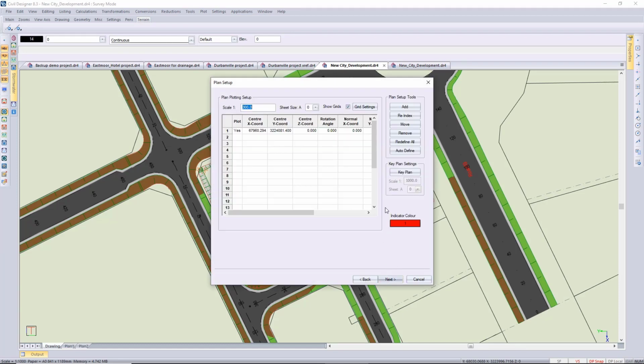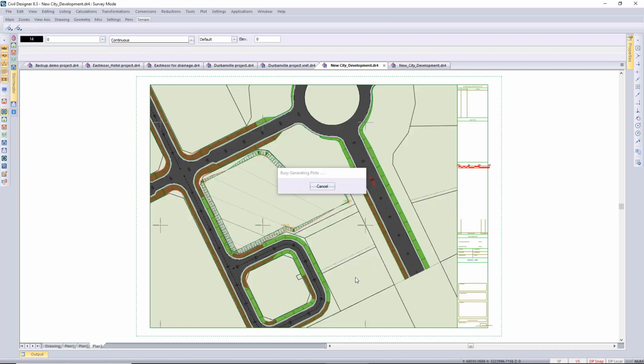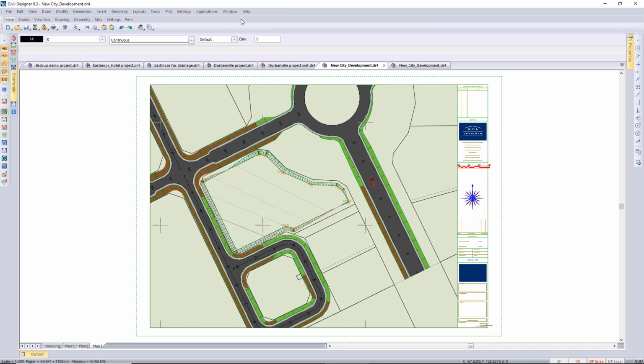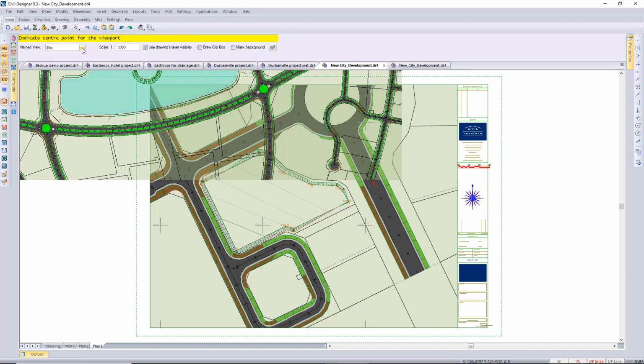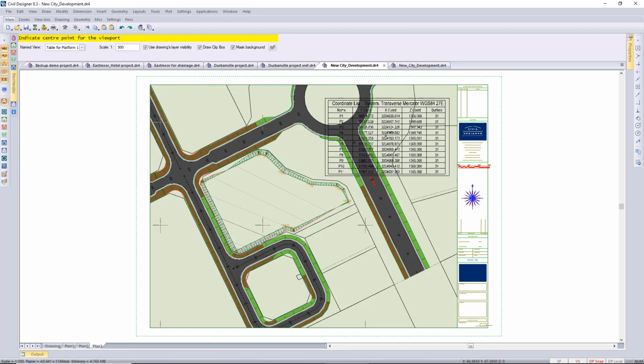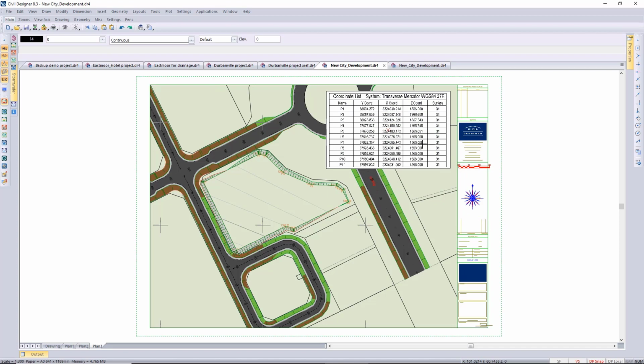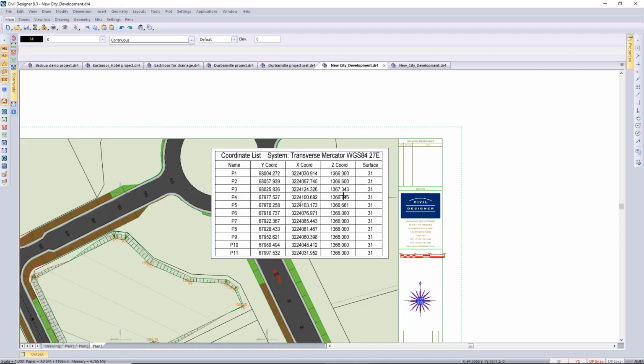Using that same define plot area, I'm switching off that list to plot because we're going to load the viewport. So that would be in the CAD, unless using the toolbar, we can go layouts, add viewport, and select the correct viewport. You can draw a clip box and you can mask the background behind your table. Probably just need to scale it a little bit in this case. You can see how it clips out the background. And this table looks a lot neater. You can see all of the columns have been centralized.